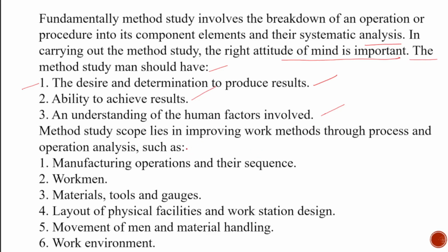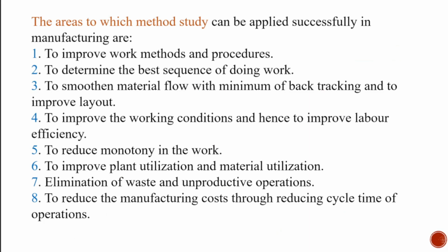The method study scope lies in improving work methods through process and operation analysis, such as manufacturing operations and their sequences, workmen, materials, tools and gauges, layout of physical facilities and workstation design, movement of men and material handling, then work environment.